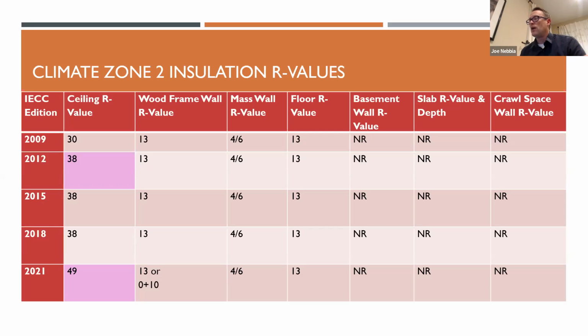So that's an amount of insulation. And again, I can't stress this enough because it does get very confusing in code compliance. Effective R value is not a thing in the code. Labeled R value is a thing. U value is where we start to take in things like drywalls, air films, framing factor, how well that wall performs as an assembly, a whole assembly.